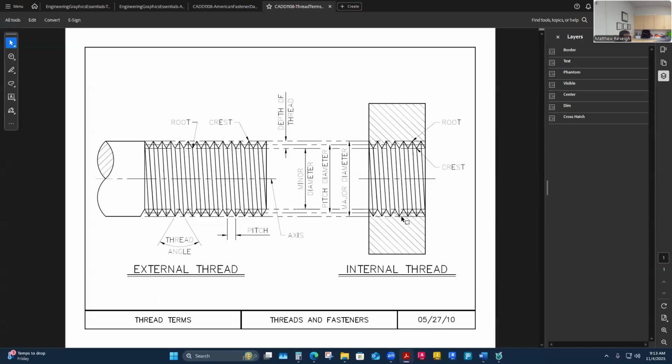Super nerdy, but if you like building houses, this might not interest you as much. But if you like building machine parts, this is nerd central here. Anyway, so many failures happen because these conditions aren't met or they've been compromised due to having experienced a load. Like if something is pulled on these threads and maybe it hasn't broken my bolt, but it's definitely compromised the internal threads.